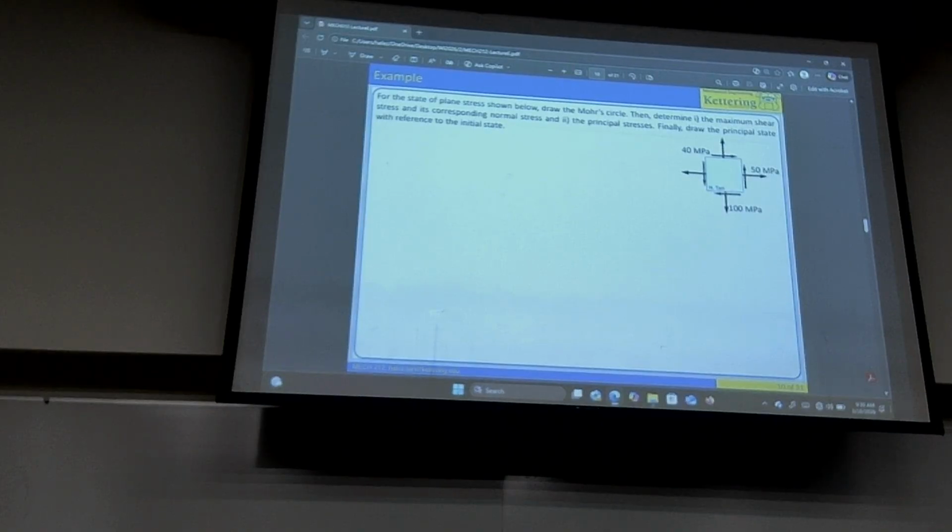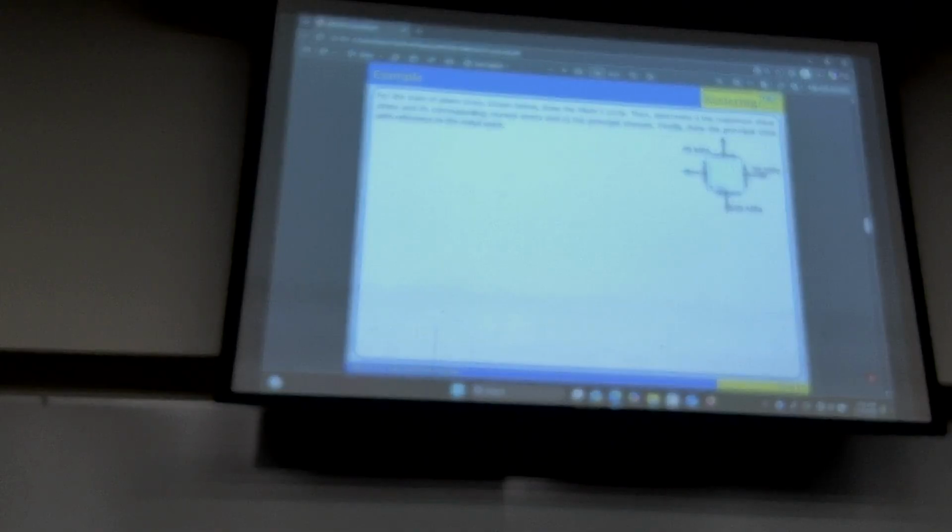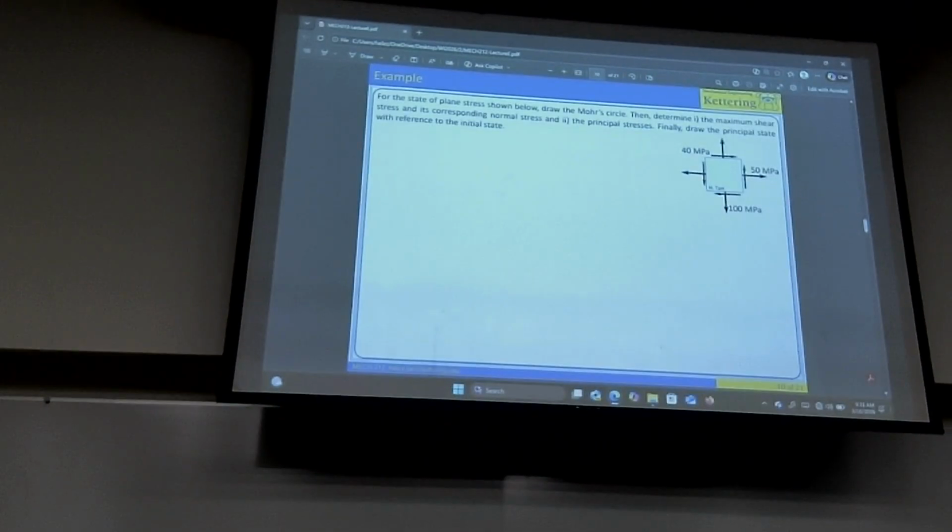All right, let's see what else I can do. Let's do this practice. Okay, it's Drew. Drew, picture the Mohr circle. We know that every point has 2 coordinates, right? On the plane, x, y values, 2 coordinates, 2 values. But here the coordinates are sigma and tau. Sigma is horizontally to the right, tau is vertically downward. Picture that. Give me the locations of sigma max, sigma min, and tau max.